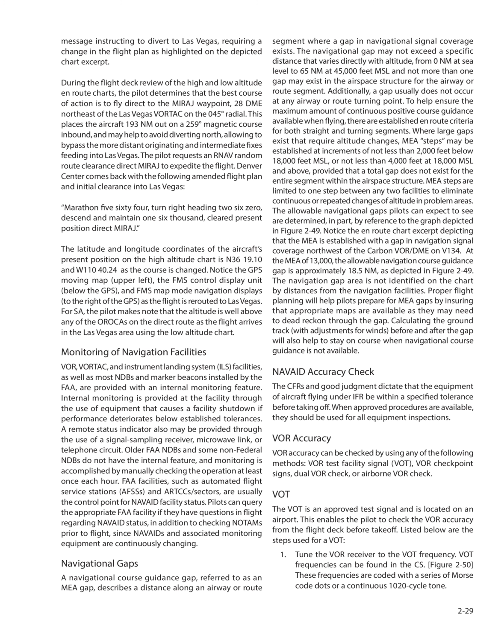FAA facilities, such as automated flight service stations, AFSSs, and ARTCCs/sectors, are usually the control point for NAVAID facility status. Pilots can query the appropriate FAA facility if they have questions in flight regarding NAVAID status, in addition to checking NOTAMs prior to flight, since NAVAIDs and associated monitoring equipment are continuously changing.